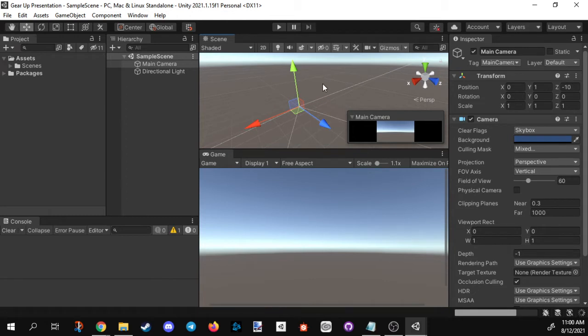This is where Unity and Blender differ slightly, where in Blender, your z-axis was vertical. But in Unity, your y-axis is the vertical one. So you can see right here, this green arrow, it's just slightly different than Blender. It doesn't really matter if you're just using the arrows, but just be mindful that if something is asking for the y-axis, in Unity it is vertical, the one that goes straight up and down, but in Blender it's not. So just be aware of that.